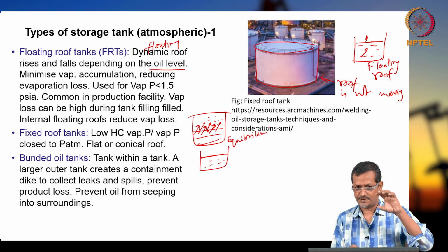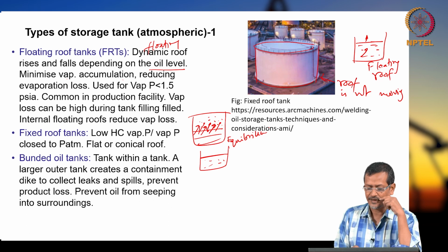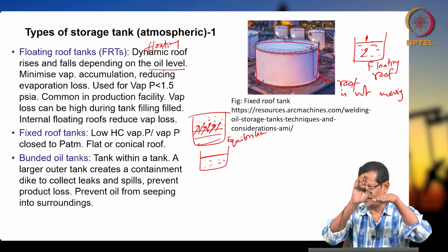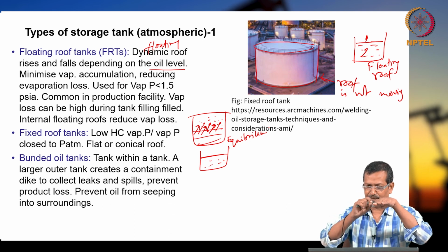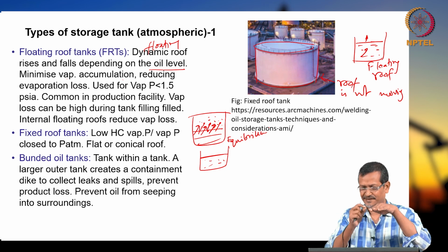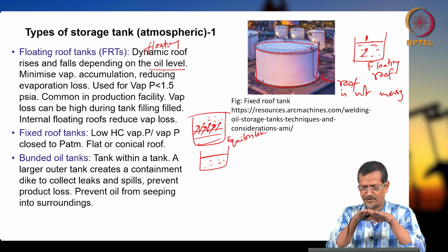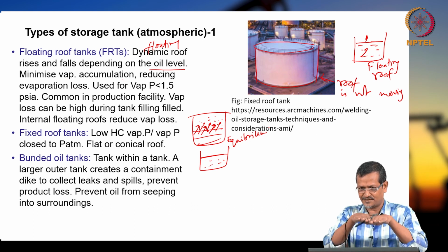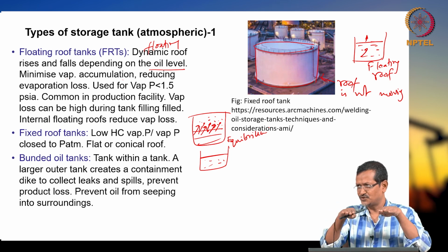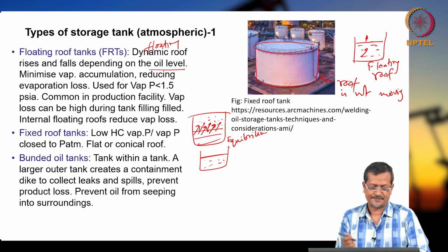So, the vapor space will have a certain, fixed amount of vapor. But if you have that floating roof, the floating roof means it is not allowing vapor particles to move up. So, the vapor particles will not get any Brownian motion. Brownian motion means it will be leaving, then it will be moving randomly, right. But when you have a floating roof touching the surface, particles not leaving, so there is no Brownian motion. So, vapor loss will be lower in the floating case.